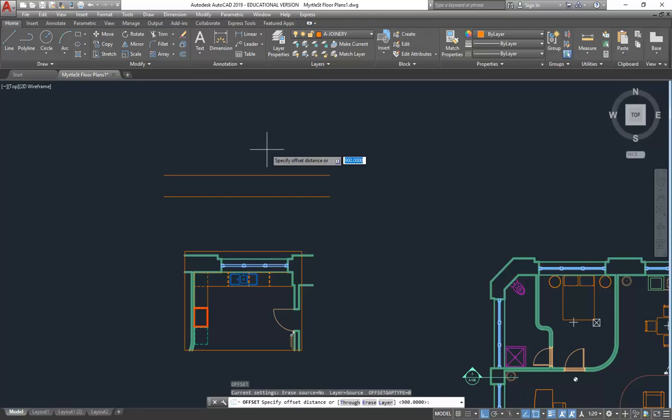So bricks, it's 600, but 7 courses fit into 600. That's how you work out the height of your bricks. And so it's the same with kitchen units, joinery units, lots of things will divide up in increments of 300, but don't take it as a golden rule. There's always going to be adjustments for different things as well. So that makes it easier to remember these heights.